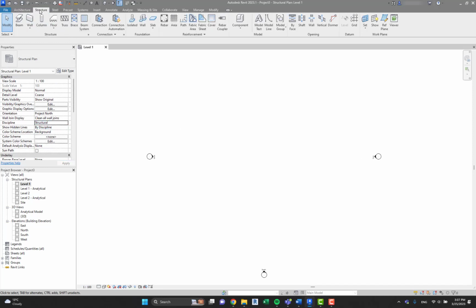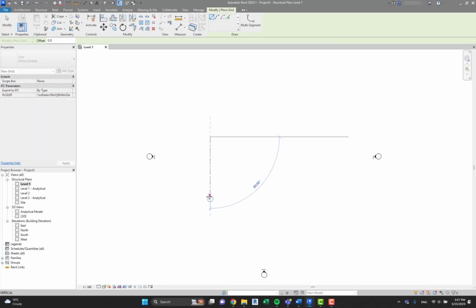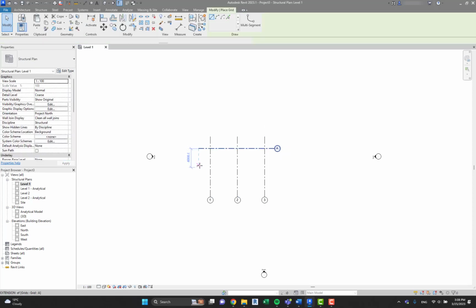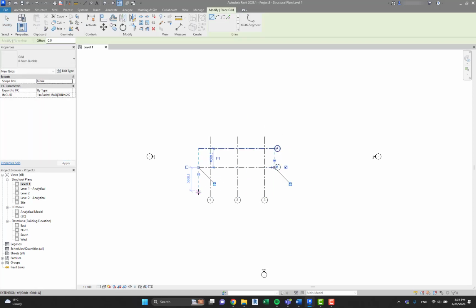Let's start modeling using the structural tab because I'm currently working in the structural template. I want to create a grid system on which I will build the project. As you can see, it numbers them automatically. But if you switch from vertical to horizontal and want the grids to have alphanumeric numbering, you need to change one of them manually, and afterwards, it will follow the rule.